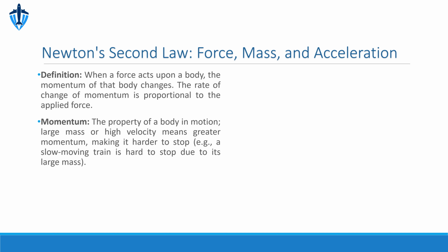To determine the gear reduction, we divide the number of teeth on the ring gear by the number of teeth on the sun gear. In our example, with an 82-tooth ring gear and a 28-tooth sun gear, the gear reduction is 82 divided by 28, which equals 2.93. This signifies that the engine is rotating 2.93 times faster than the propeller.